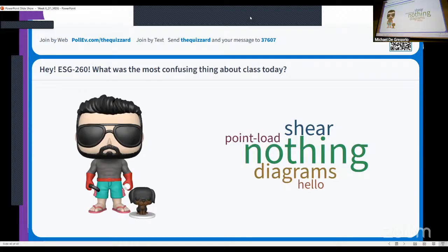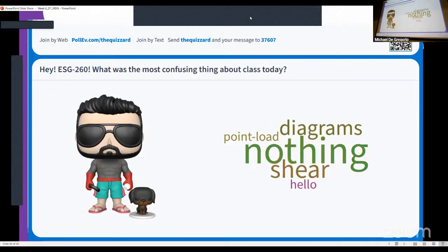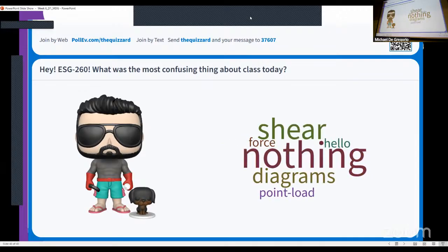They're telling you that at the vertex of that triangle, you have 8 kilonewton per meter. So yes, it's going to be 8 kilonewton per meter at that. For this one, yes, you're absolutely right. You've got to first find this guy here. I would split this into 2 triangles and create 2 forces, still using 8.